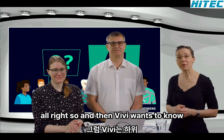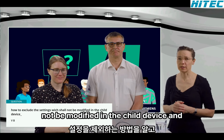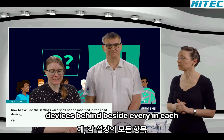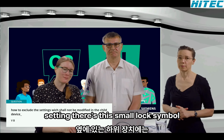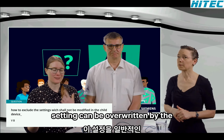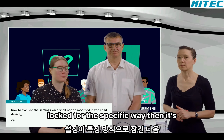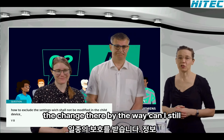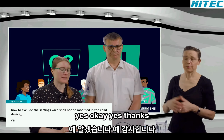All right. And then Vivi wants to know how to exclude the settings which shall not be modified in the child device. And I think you showed that with this little lock symbol, right? Yes. So in the child devices, beside each setting, there's this small lock symbol. If this lock is open, these settings can be overwritten by the typical base settings. And if this lock symbol is closed, then the setting is locked for the specific bay. Then it's kind of protected against the change there. By the way, can I still change the information? Yes, you can.